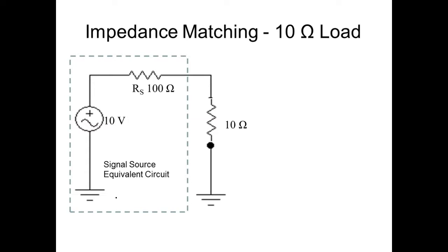Now, we fake that out with something that's dynamic, like the alternator on your car. When you turn on your lights, we have what we call a voltage regulator that senses when the voltage tries to go down, and it puts more energy into the generator to make it maintain that, right? You understand? So if I don't have a regulated circuit and I've got a power source without a regulator, then as soon as I put a load on that, the output voltage is going to drop.